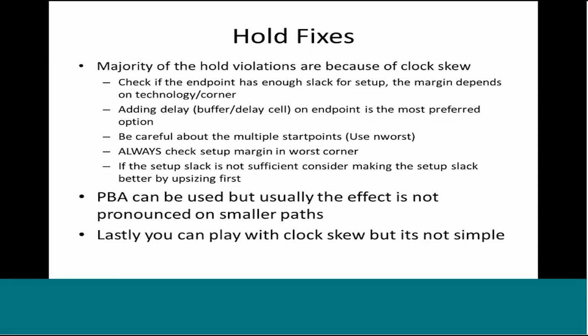And so the first thing that should be checked before fixing any hold is that the first priority is adding the delay at the endpoint. So if you add the delay on the endpoint, let's say if you insert a buffer at the data pin of the violating endpoint, then you are made sure that even if there are multiple start points, multiple clocks driving this logic, then also the hold timing will remain fixed, because we are fixing the endpoint. Probably this will not make sense now, but when you start working on some real projects, you will understand the significance of it.